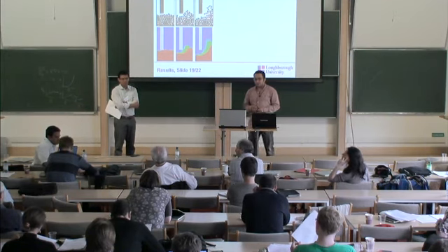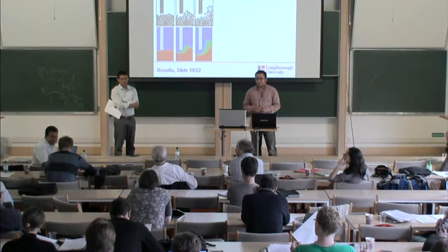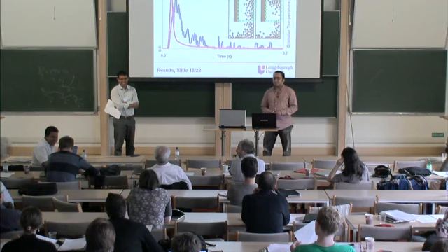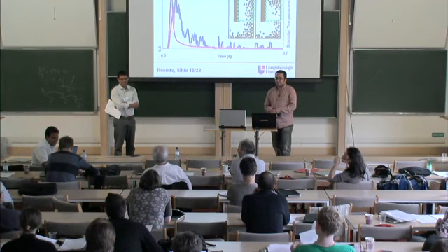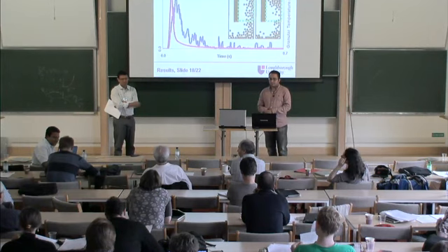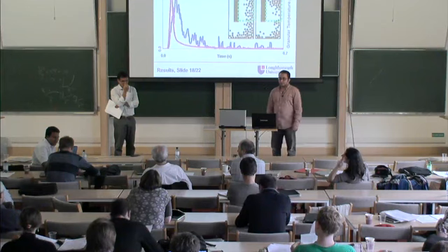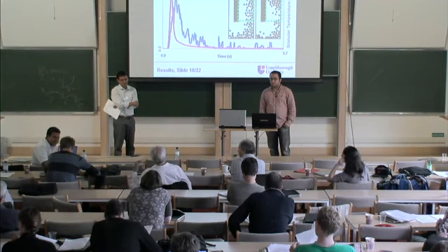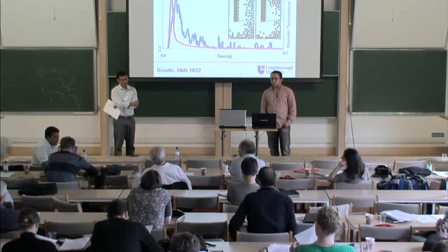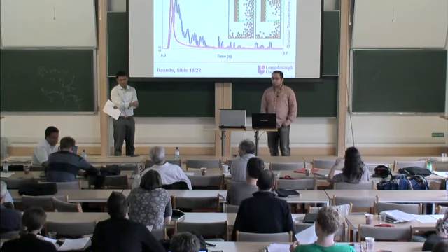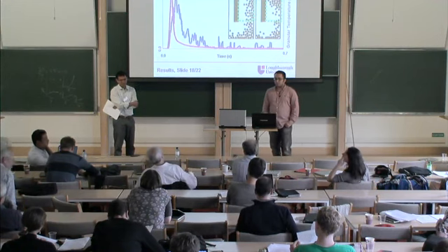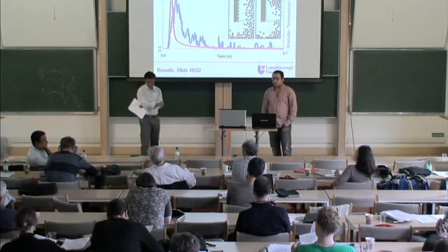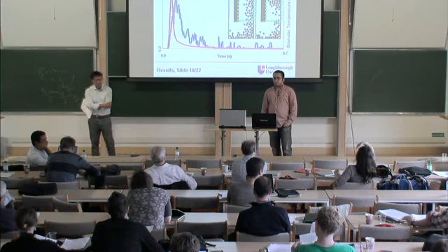Okay, first of all, I have to say I did not measure the granular temperature in a fluidized bed. I measured the particle pressures exerted on the wall, and I don't think they're honestly related to the granular temperature. They're related to defluidization of the bed by the passing bubble, and the stresses were largely elastically distributed out to the wall. But I have sort of the same question, and that is, what did you subtract off? What was the mean velocity you subtracted off, and how could you differentiate the thermal fluctuations from turbulent, that is, ordered fluctuations between the particles?